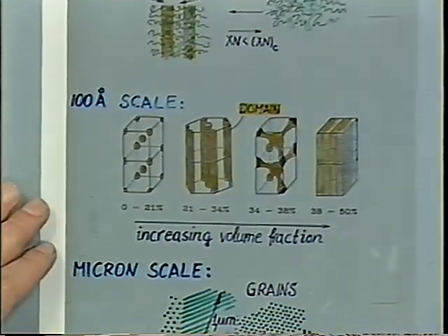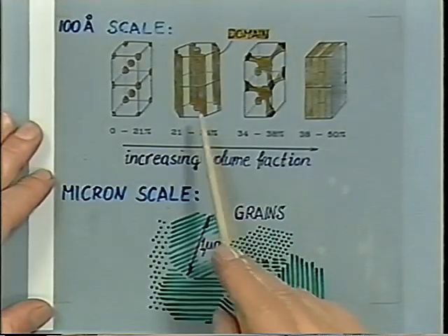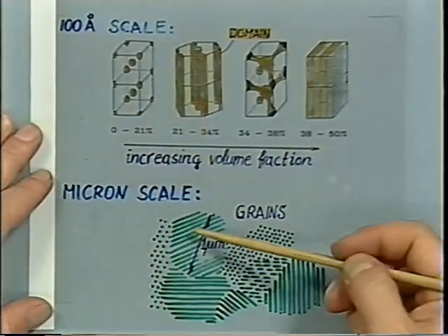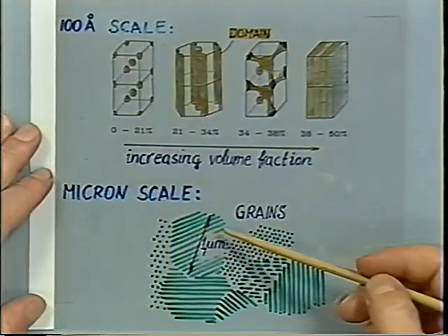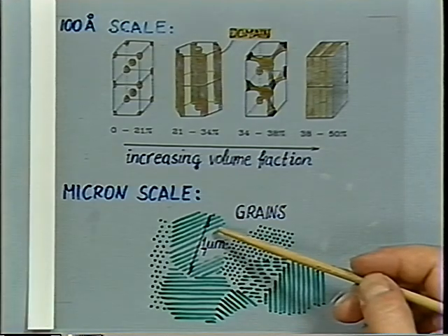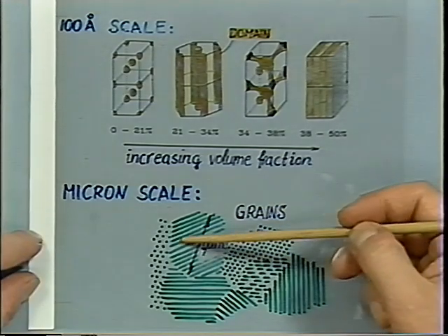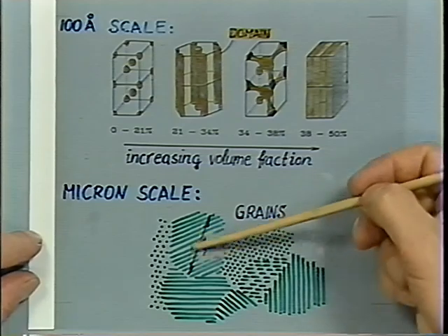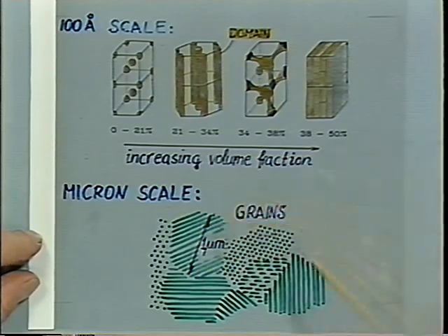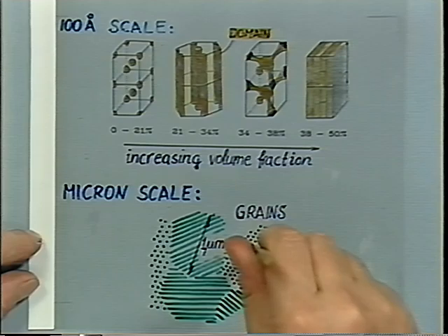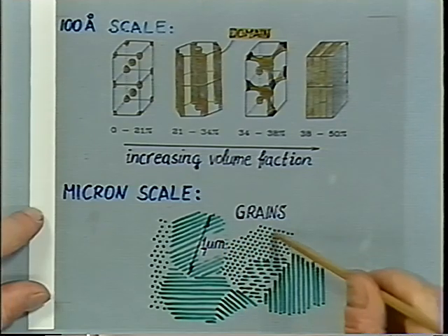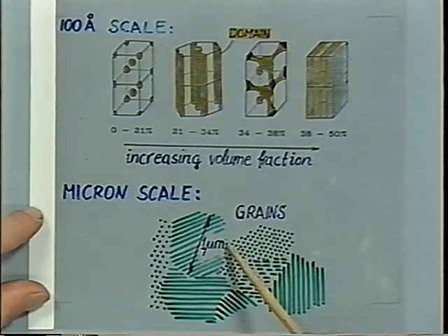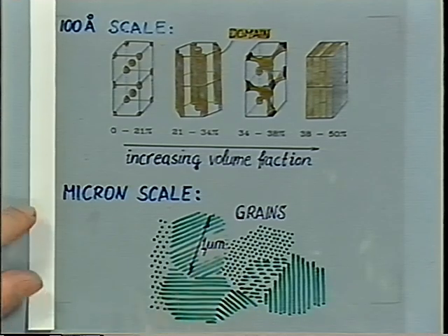On an even larger scale now, those ordered regions seem to form in a nucleation and growth mechanism when you get them from solution. So there's one region maybe ordered and it's growing and forming a grain, and there are other regions having an initial order which is different and also forming a grain, the boundaries are discontinuous, but within a grain, the order is fairly homogeneous. The fluctuations might be very, very small.